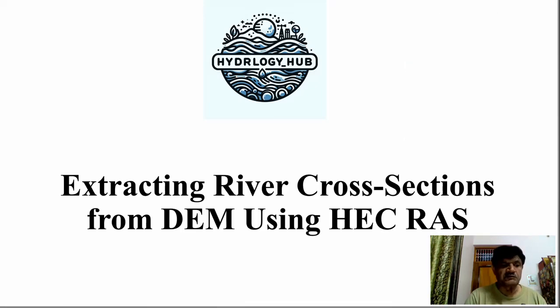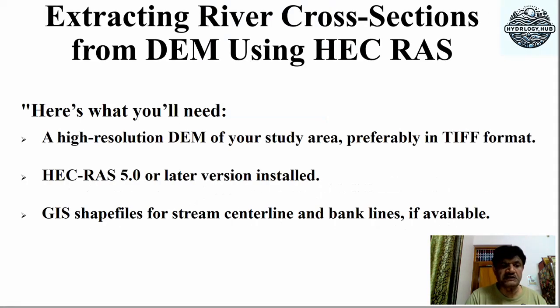Here is what you will need: a high resolution DEM of your study area, HEC-RAS software of the latest version, GIS shapefiles for stream, center line and bank lines if available. But don't worry, I will show you how to digitize each of them.